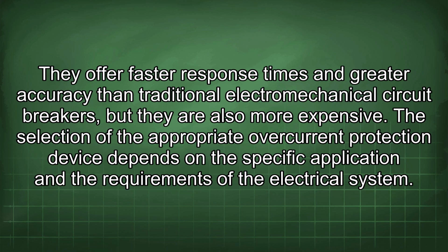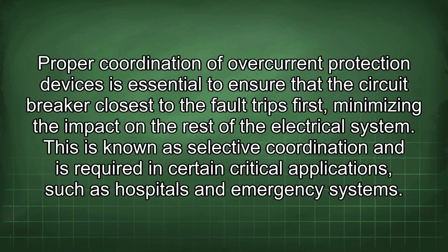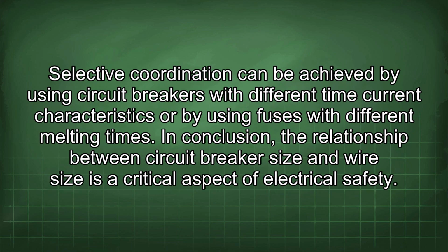The selection of the appropriate overcurrent protection device depends on the specific application and the requirements of the electrical system. Proper coordination of overcurrent protection devices is essential to ensure that the circuit breaker closest to the fault trips first, minimizing the impact on the rest of the electrical system. This is known as selective coordination and is required in certain critical applications, such as hospitals and emergency systems. Selective coordination can be achieved by using circuit breakers with different time current characteristics or by using fuses with different